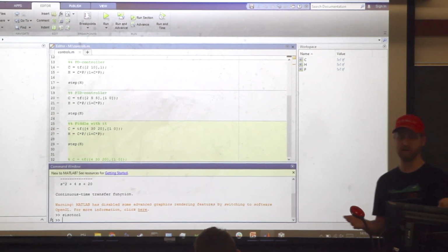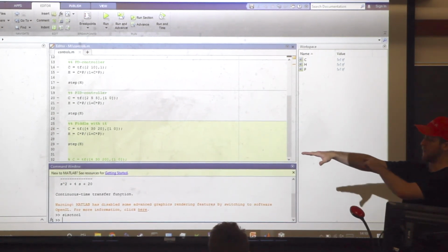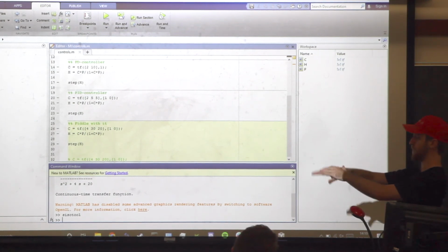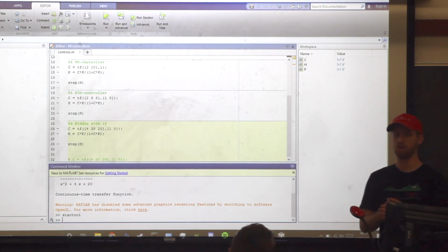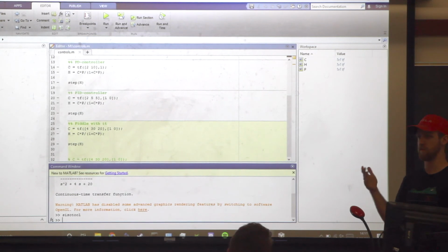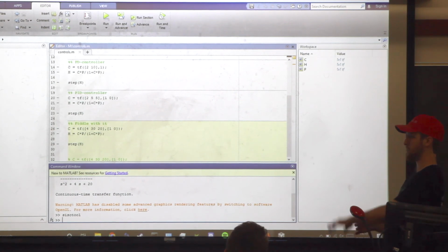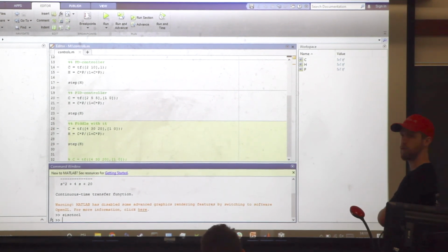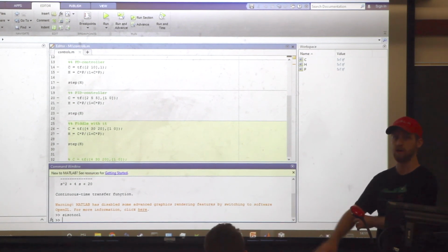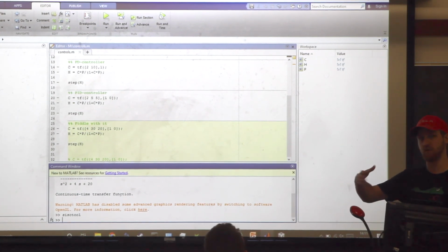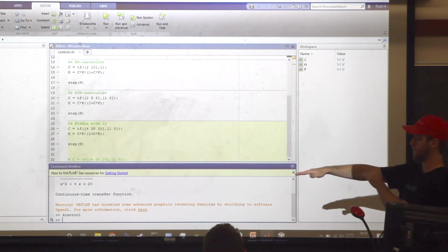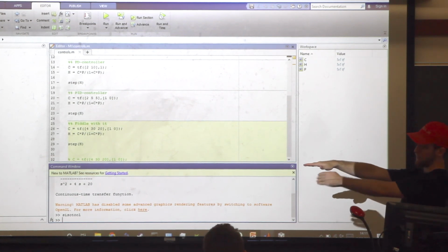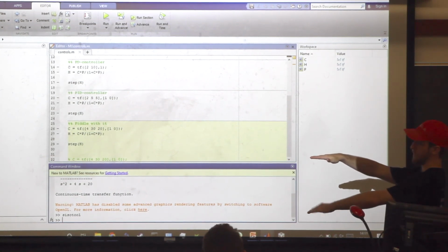Basically, if you look at those charts, you'll end up with a line, and that'll show you a response to various frequencies. Depending on what class you take, you may know that you can represent any function as a series of sine waves. It's called a Fourier series. And essentially, you'll look at what you expect to happen, and you'll say, okay, maybe you want to get rid of high frequency inputs, because maybe you have a sensor that's got some noise in it, so it's kind of going like this. You want to get rid of that and only look at the big picture. So you'll end up with a line, and your frequency will be here, and your amplitude will be here.